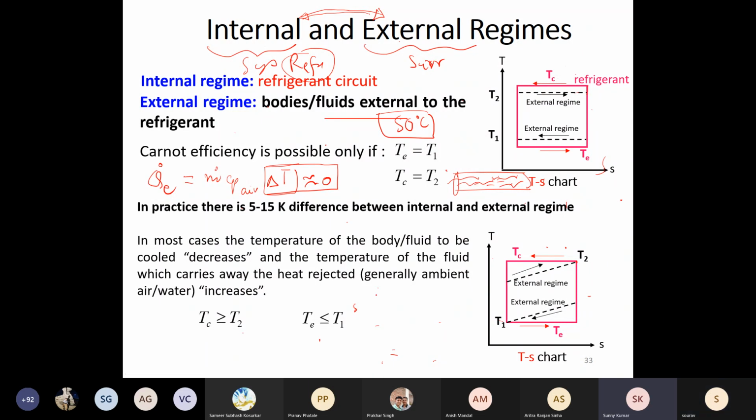That is, he always stated that there are two thermal reservoirs, and the definition of a thermal reservoir is it will have MCp tending to infinity. So no matter how much heat you dump, the ambient temperature will not rise. This is what we assumed previously, and the outcome of this is global warming. So even the entire atmosphere is not a thermal reservoir, because it doesn't have an infinite mass, it doesn't have an infinite Cp.